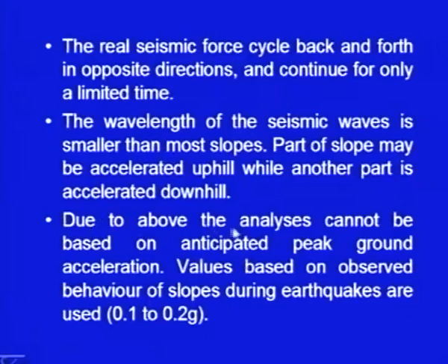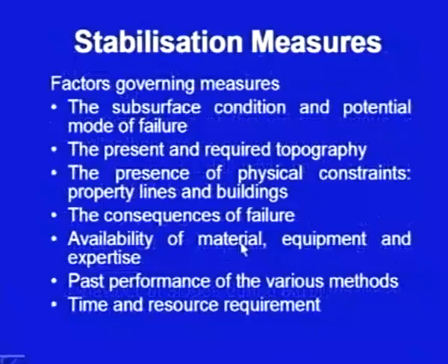So, due to the above reasons, the analysis cannot be based on anticipated peak ground acceleration. Rather, values based on observed behavior of slopes during earthquakes are used, and this coefficient varies roughly between 0.1 to 0.2 g. So, this is an approximate method.